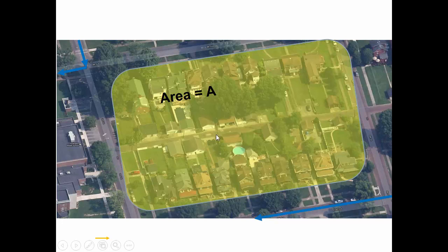So once we have this area defined, we have to understand the travel time. Like a raindrop that falls right next to the grate would get into the grate within just a few seconds. But one that falls here, well, what is the path it has to take and what will be the speed as it travels over that path? So water maybe would flow along the road for a little while, and then it would go down this way and get into the grate. And so you'd have to know the travel time, and you'd find the travel time that's the furthest away.